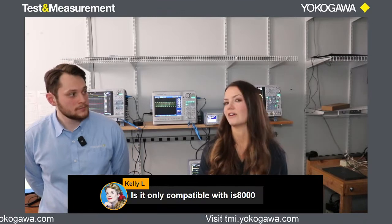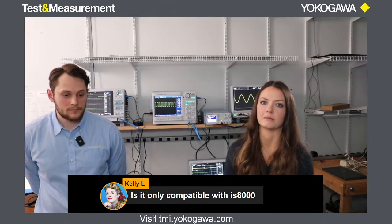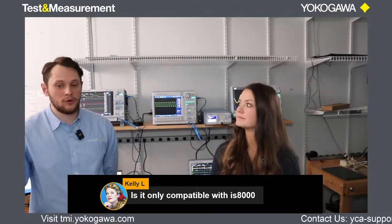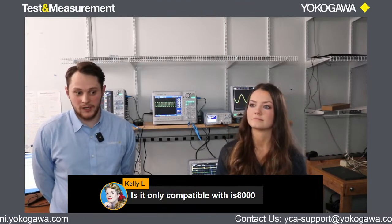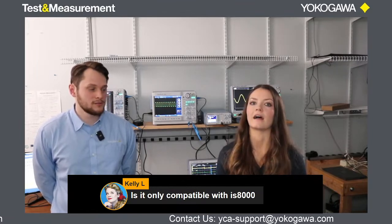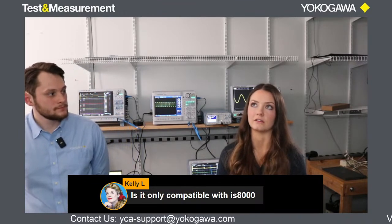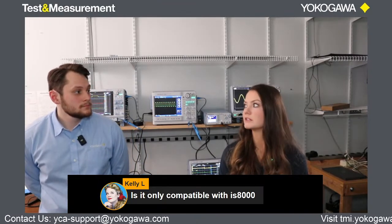Anything I missed? That would be if you want to use it with Python or LabVIEW or C++. There's also the web server, so you can interact with it straight through the Ethernet port. You log on to the IP address, and remote control is one of the important things through the web server. It doesn't do the same data output, you can't output data to a CSV, but you can pull data from the 5000 onto your computer using the web server.